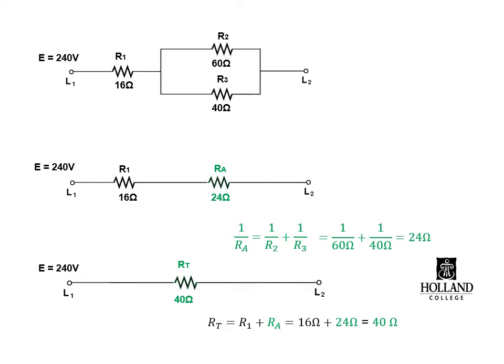The procedure is to simplify down to a simple series or a simple parallel. In this case, we simplified it down to one single resistor, RT. Now that we know what the total equivalent opposition is, we can now calculate IT. We have found everything for that third row. We have the voltage, the current, and the total resistance. We can now move up or back one step.